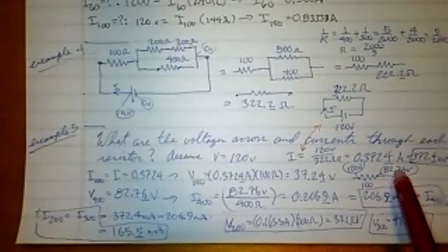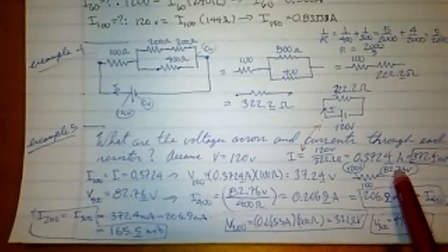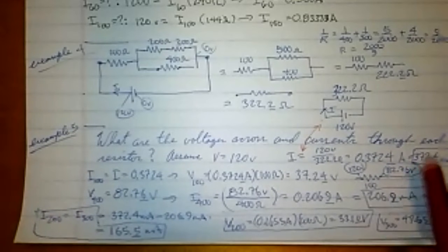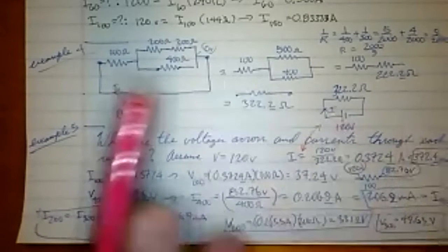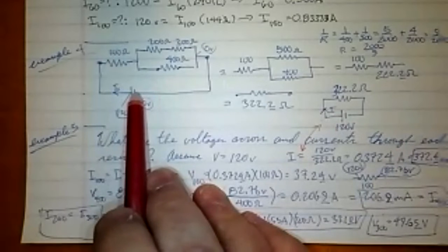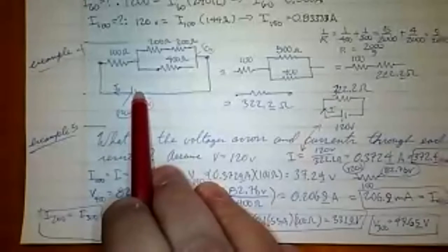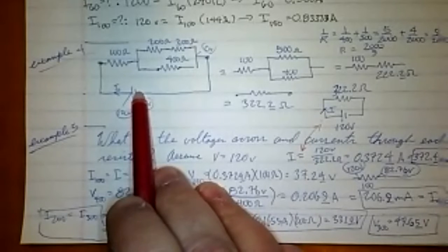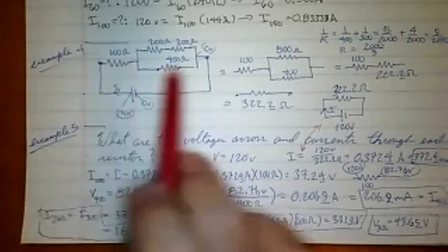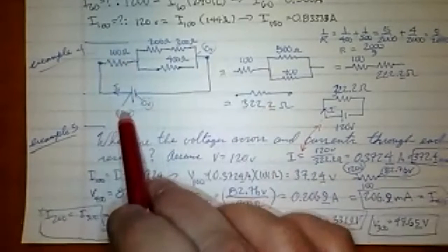Y'all see the difference between the voltage across and the voltage at a location? That's sort of the weirdness of this. What you can think of this one as is if I stuck the black probe of my voltmeter right here, or stuck it directly in ground, which I'm assuming is what this side is. And then I stuck my red probe anywhere on the circuit. That's what these little bubbles I keep popping up are.